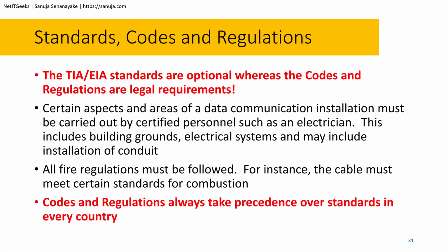Standard codes and regulations, they are similar, but they are not the same. The TIA or EIA standards are optional, whereas the codes and regulations are legal requirements. As I mentioned before, some standards may follow exactly how the regulations or codes are written, but some standards do not follow that. Therefore, the EIA and TIA standards are optional, whereas the codes associated with structured cabling are legal